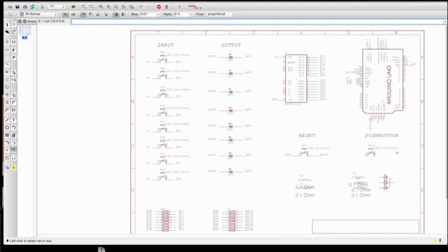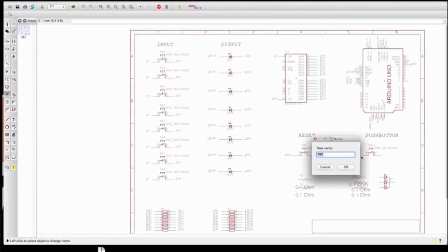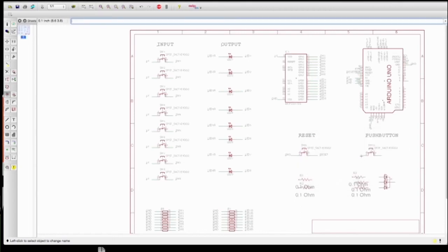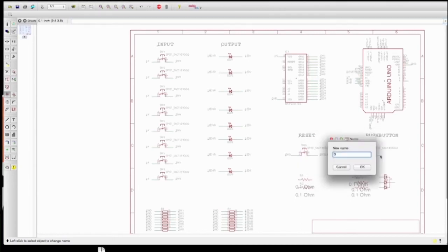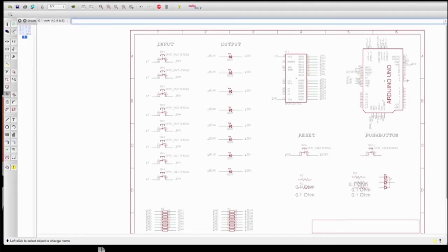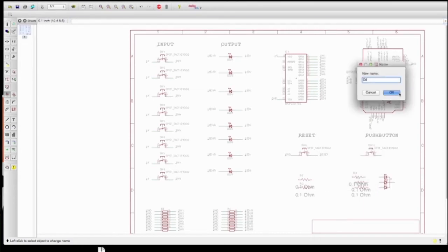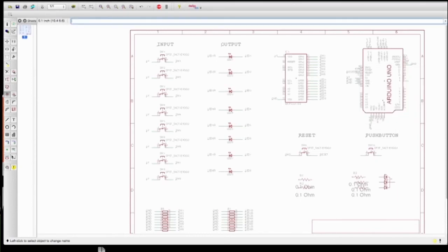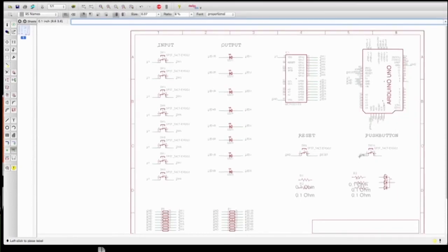And let's see, we have our push button. Let's look at the drawing here and see where the push button went before. It went to D8. So we're going to do something very similar here too. We're going to connect up wires like this, and I need D8. So we're going to run on the D8, and we're going to name these. This side's going to be ground. This side is going to be D8 for digital pin 8. That makes sense, right? D8 and D8, just like that.